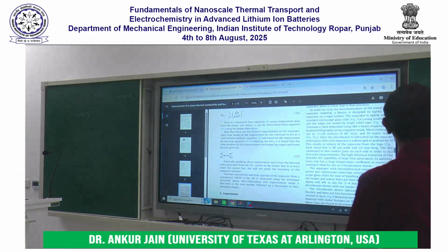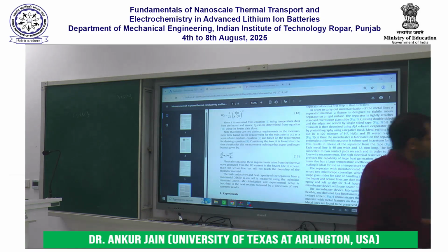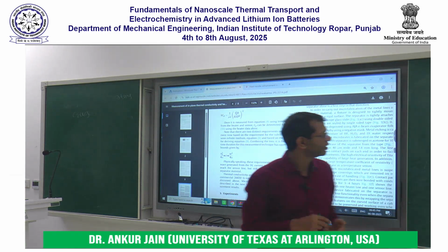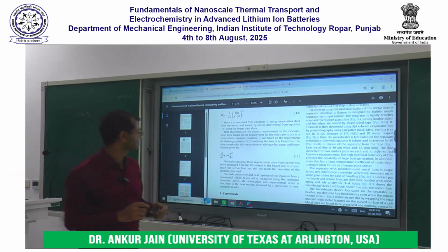So basically there is a source of the metal, and you take an E-beam gun and you shoot on the source, which ejects the metal atoms, and they go all over, and obviously most of them will be intercepted by the mask, but some of them will pass through the hole in the mask, and the shape that you obtain on your substrate corresponds to the hole in the mask. Right? This is a common technique. This is easily done in any lab. You just need a couple of key pieces of equipment, but other than that, this is easily doable.